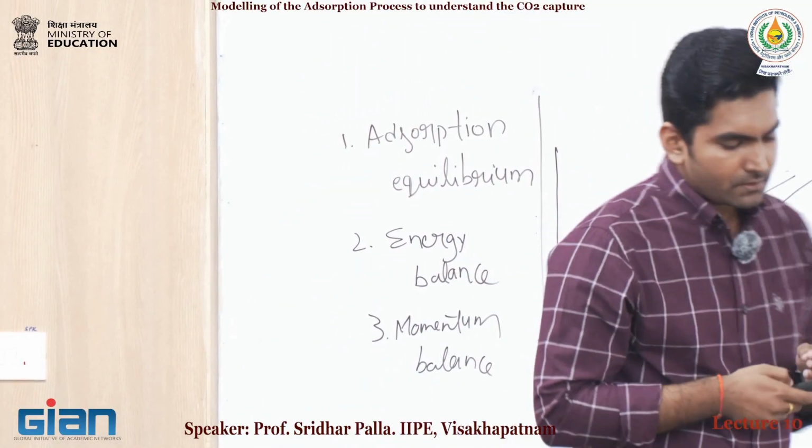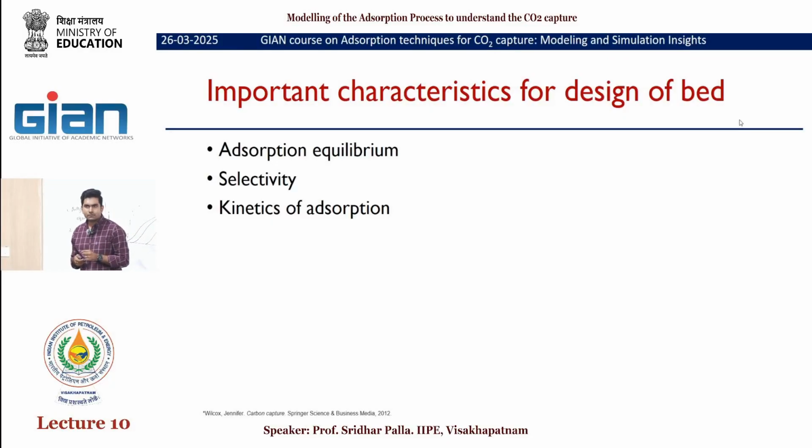Kinetics, we will get that information from the breakthrough curves. We have linear driving force models, and a couple of other models which will pass this information to the mass balance equation.